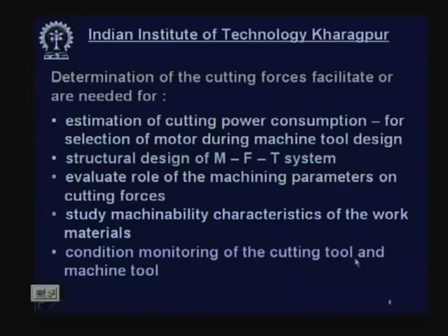Condition monitoring of the cutting tool and machine tool. During machining the cutting tool undergoes gradual wear and tear. Sometimes it may undergo very rapid plastic deformation because of high temperature and pressure. Whatever be the case, the tool becomes dull, and this is very undesirable. If it becomes too dull, then we have to replace it. We have to withdraw the cutting tool and replace it immediately.